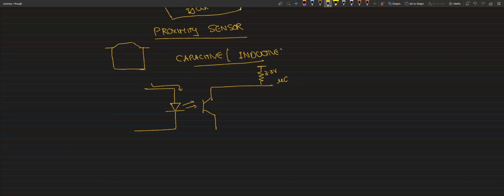This is purely communicating through light. Even if there is a high voltage, this LED may spoil, but it is not affecting our digital circuitry. This circuitry may be operating at 3.3 volts or 1.8 volts, but this side will be operating at your AC voltages, high voltage. By mistake, if it were coupled to the 3.3 volt, the entire digital circuit would be burned. So that's where it won't get damaged now because of this interface.